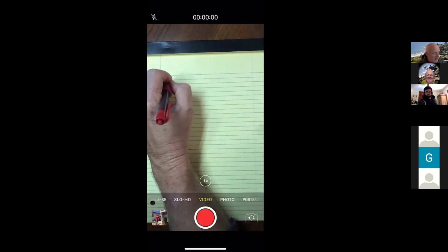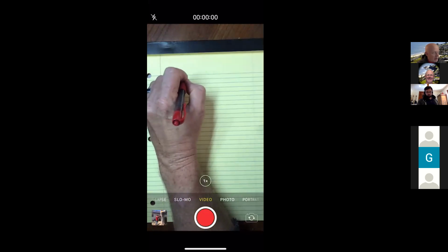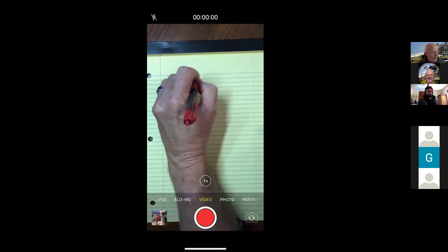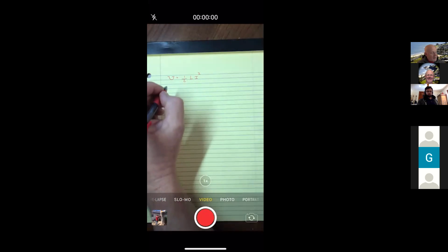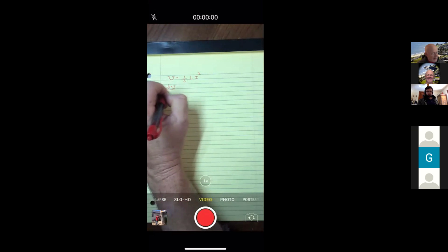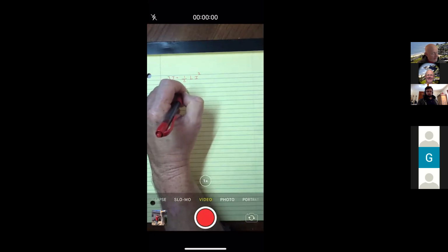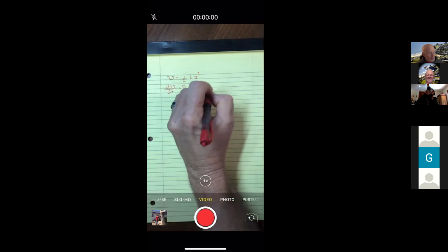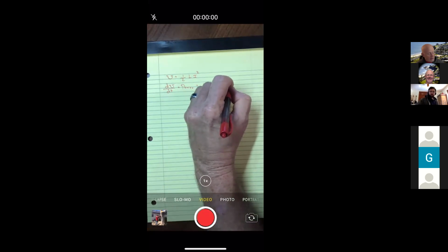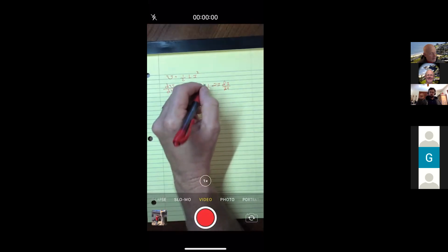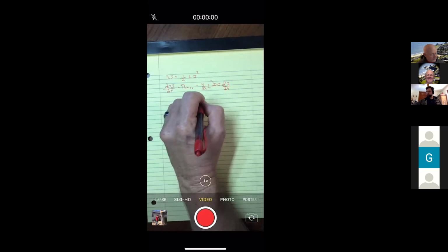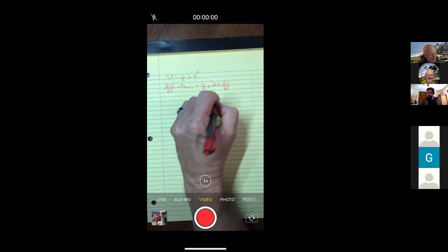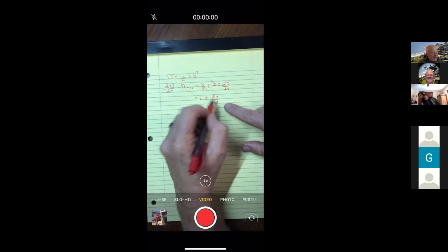Yeah. And let me say it a little differently though, because it's really based on this. The energy in the inductor is 1/2 Li squared. And if you then take the derivative with respect to time, that's called power. And you get this equation. You get a 1/2, you get an L, you get a 2, you get an I, and there's the magical key, di dt. I'll cancel the 2's, but the one I want to focus on is right here, di dt.